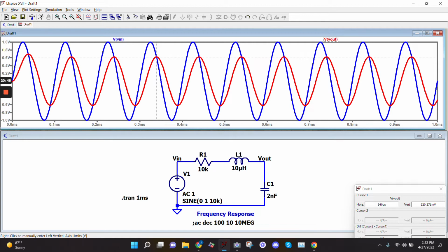But it's another thing that makes the hand calculation and analysis of this stuff easier to do by hand, because then you can just draw a straight line and a straight line. It makes the hand calcs easier. But looking at it in Spice, I almost always just tell people to switch this to linear because the decibels just don't make sense. I don't know what they are. 0 dB is 1 volt, or a ratio of 1. But like I said, I'm not going to get into that. I just wanted to show you that this worked. So everyone should at least see that this worked at the frequency I said it was. I got the magnitude I said I would.